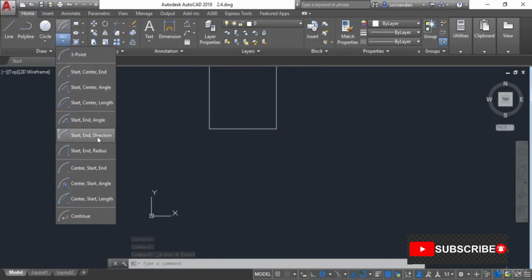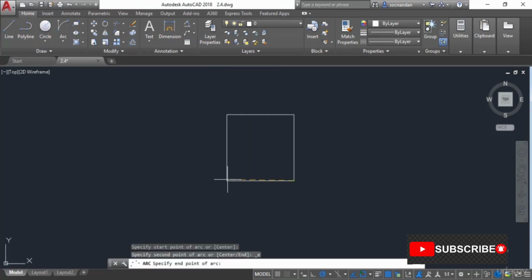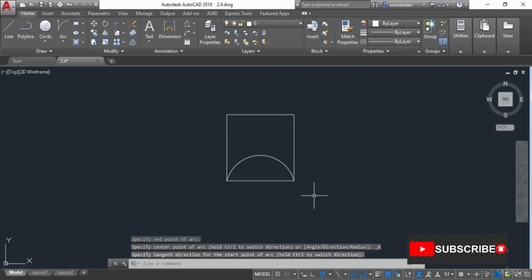Now the next option is start and end direction. Once again, here we have the starting point, then the end point, and now the tangential direction. Here you can see that as I move my cursor, the tangent line is moving, and also the radius of the arc is changing. And here we can change it directly, but this dotted line is always tangent to this arc. Now if you want to change the direction, you can simply hold the control key and the direction will change just like this. And this control key will also work for all the remaining arcs which we have drawn so far. So let's release the control key, and now let's click anywhere in the drawing area to make the arc.